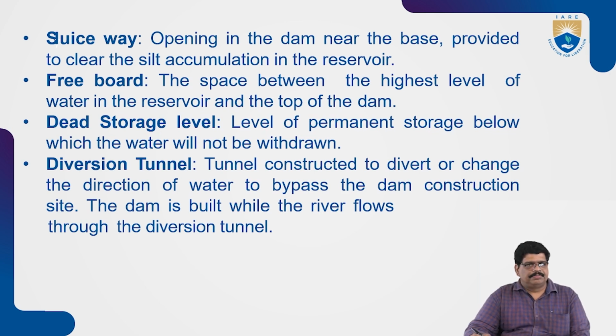Next, dead storage. These definitions are very important to understand. Dead storage is the level of permanent storage below which the water will not be withdrawn. Some of the water can be stored continuously for fisheries. Also, it can be kept for strengthening the dam. That is the purpose of storing the water. Not only that, some of the water can be utilized for emergency purposes. That's why it is the dead storage water level.